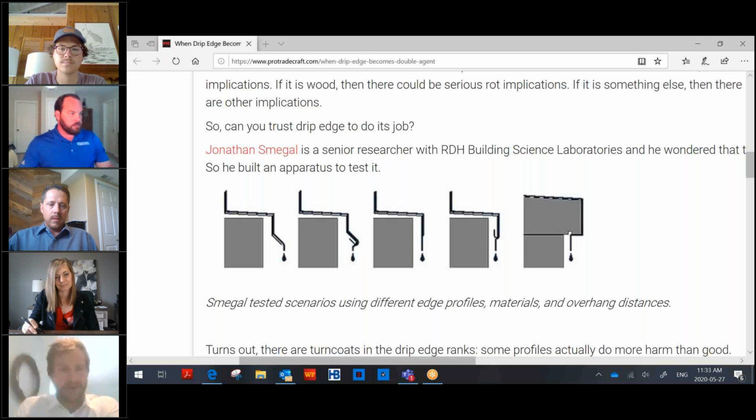I was recently watching a video on YouTube by This Old House on the importance of a drip edge for a roof. So I wanted to share a screen on the concept of a drip edge as part of through wall flashings and what it really is meant to do. The drip edge is really, really important because it stops water from clinging to a building. It gives a break.